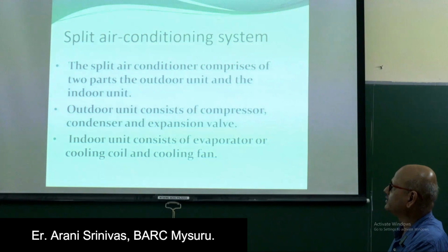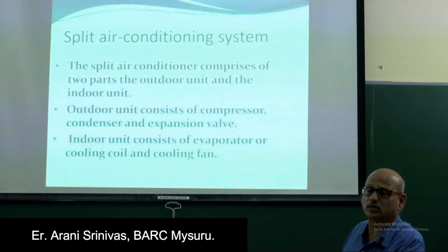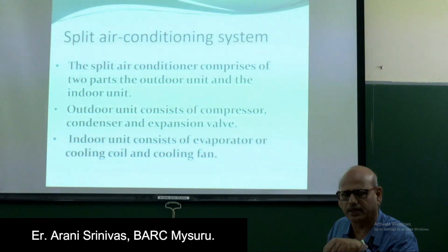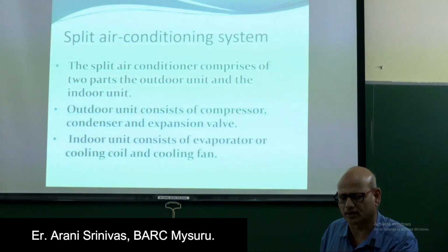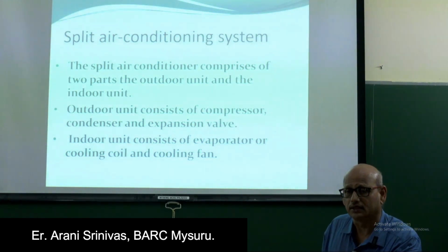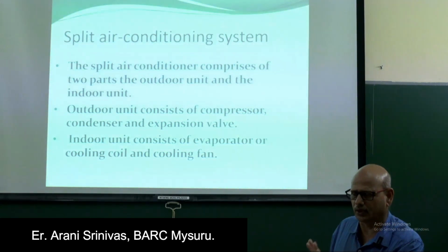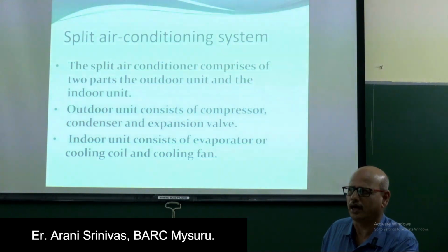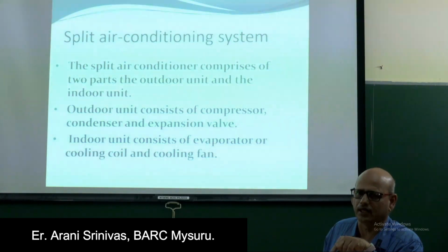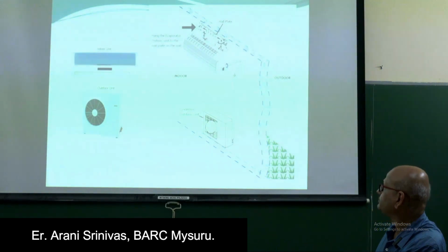See, then came split air conditioners. What happened is, when an air conditioner problem comes, think of it in a conference hall. When a meeting is going on, if there is a problem in the compressor, in the unit, we cannot go and maintain it. Then experts thought we'll try to split it. See, the evaporator we put in your meeting room, and the compressor, condenser, everything will be on the rooftop, and there will be a pipeline which runs from top to down.